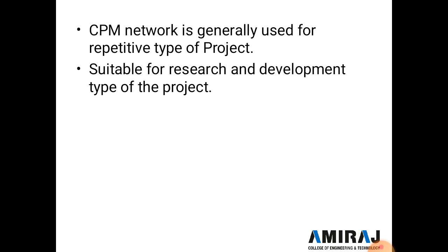Another example is a road network. We take a project of 50 kilometers to construct a road, and in those 50 kilometers all the road procedures are the same every time. So it's a repetitive type of project work, and CPM is also suitable for research and development type of projects. For research and development, a CPM network is required, because the CPM network shows the dependent and independent activities.